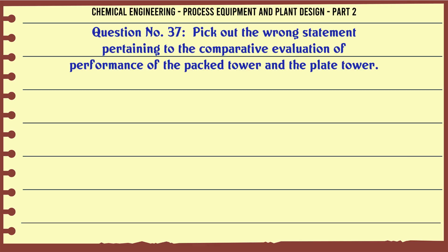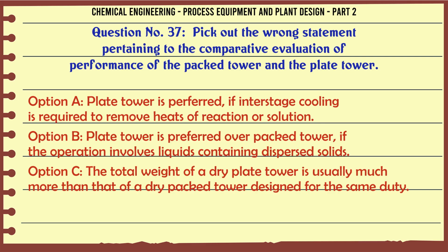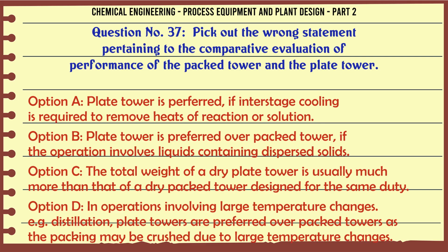Pick out the wrong statement pertaining to the comparative evaluation of performance of the packed tower and the plate tower. A. A plate tower is preferred if interstage cooling is required to remove heats of reaction or solution. B. Plate tower is preferred over packed tower if the operation involves liquids containing dispersed solids.